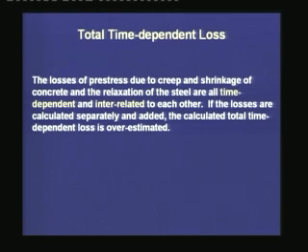Next, we are calculating the total time dependent loss. What I had mentioned before, that the loss of prestress and the individual phenomena of creep or relaxation, they are dependent on each other. That means the creep strain is dependent on the elastic strain, which is dependent on the prestressing force.